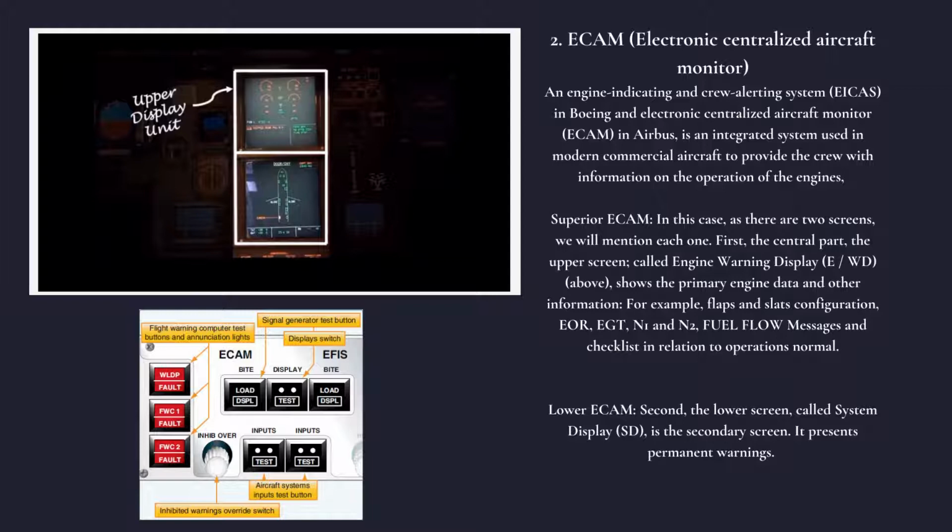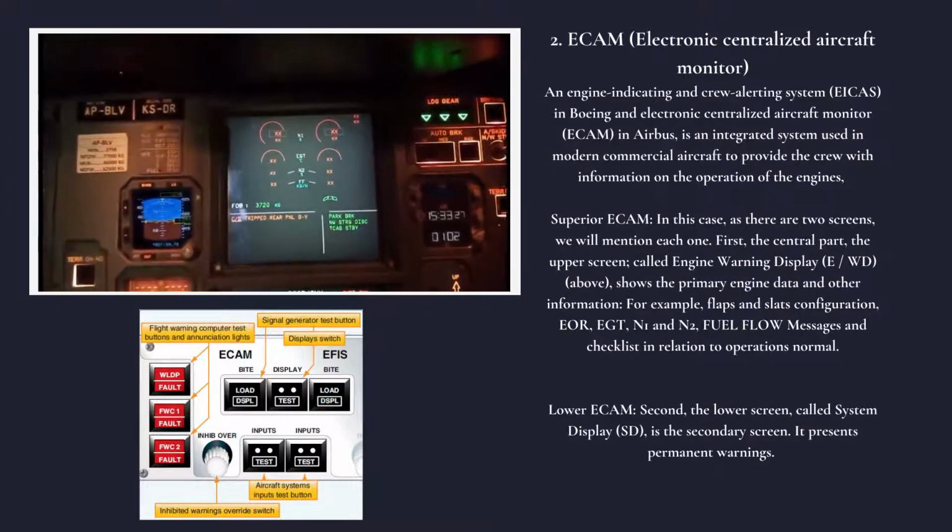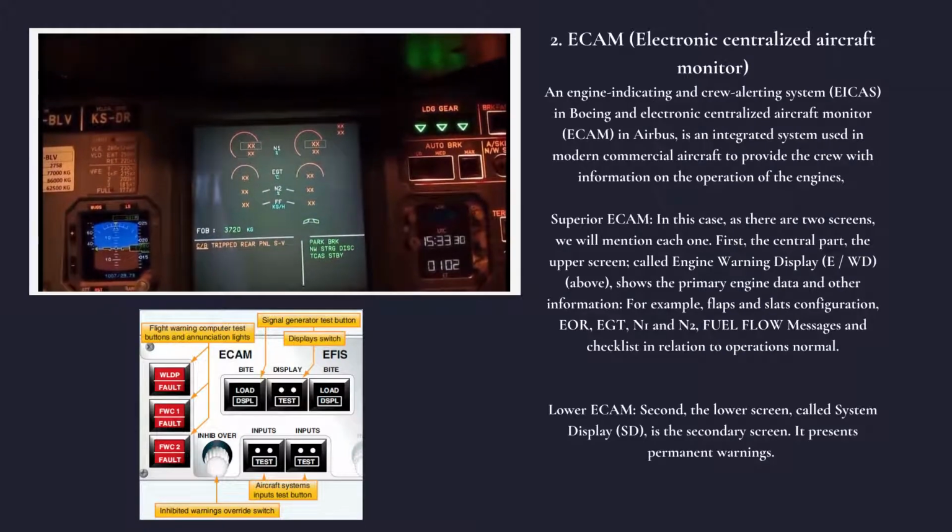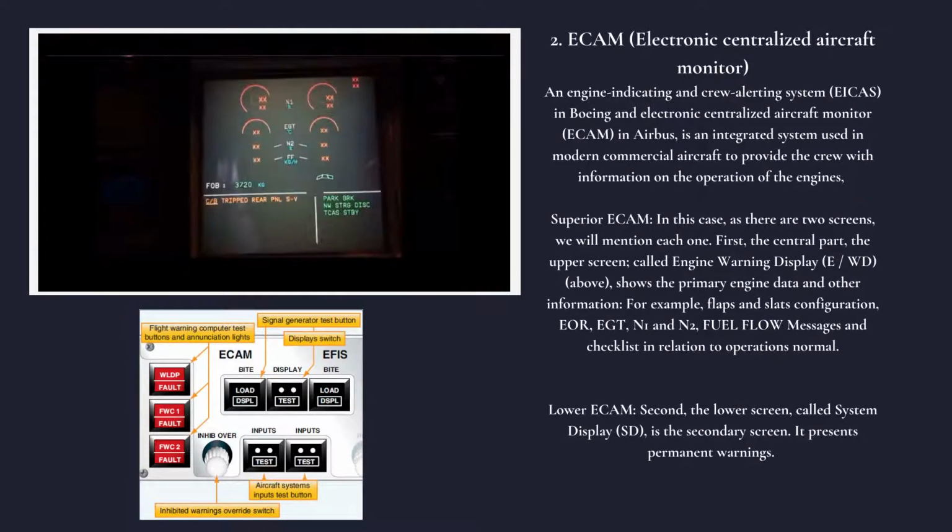The system provides us with the instrumentation of various engine parameters, including, for example, RPMs, temperature values, fuel flow and quantity, oil pressure, among others. The other aircraft systems controlled by EICAS are hydraulic, pneumatic, electrical, de-icing, control or surface systems, which replace all analog motors with software-driven electronic displays.